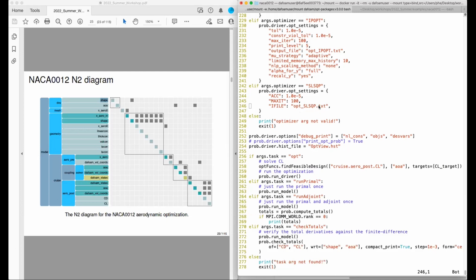For example, this MPhys interface allows you to combine different code. For example, you can combine OpenFOAM with ADflow. You can combine a VLM code with a structural solver, for example, TACS. So you can imagine that it's very hard to ask everybody to use very consistent input and output names. So that's why sometimes we have to manually connect it. Hope that answers your question.